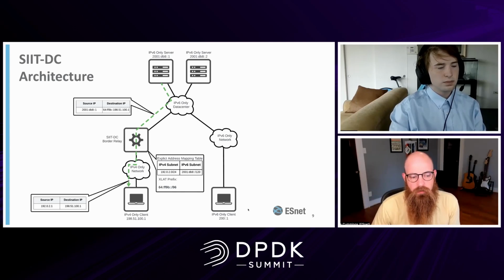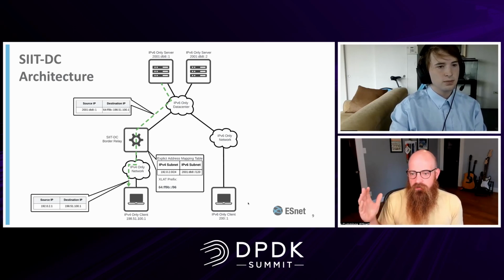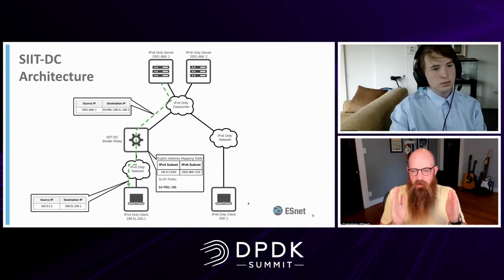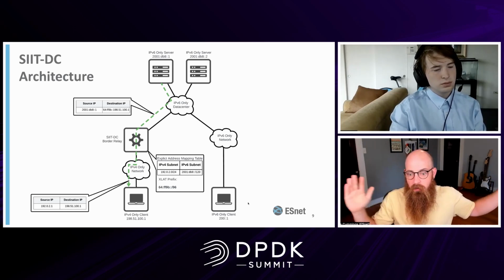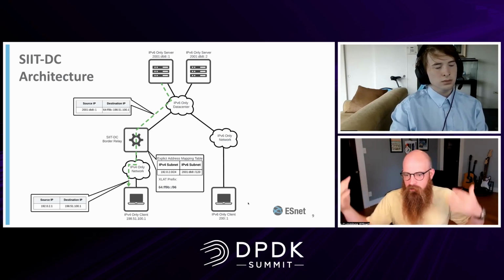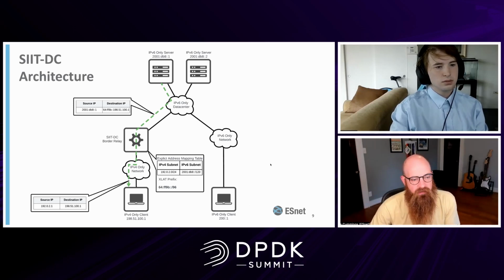So there's an example experiment that has a bunch of 25 gigabit per second FPGA data acquisition cards that are just sending data at full speed, 25 gigs all the time when the experiment's running. So using this methodology, you could have this approach scale out horizontally to as many data acquisition sensors as you have and send that across your network. So it's really nice from a stateless standpoint to be able to do that without having to do any complex state tracking and just rely on the protocol's stateless nature.